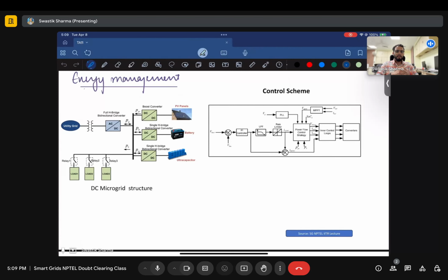And also they don't have developed protection schemes. Like for example, we discussed a few protection schemes, right? And they are all applicable to AC microgrids, not DC microgrids. And we are now currently, so why is that? Because the short circuit current is different, the way that travels from device to device is different, and that is why we need to make sure that we are developing.